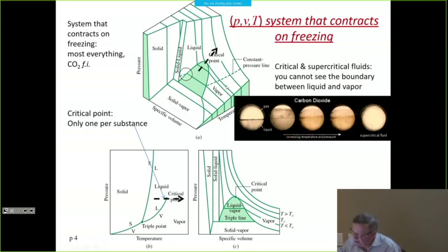Another strange property of most of these gases, liquids and solids is that there is this critical point. And there is a region above the critical point where you're above the vapor dome. In this region, the fluid has supercritical behavior, which is a little bit strange. I illustrate that here in the case of carbon dioxide. If we're here, we have a liquid and a gas that we see quite clearly. As we approach the critical point, this separation line between liquid and gas, which is very clear here, becomes more blurred, more blurred, and in the supercritical fluid, it's completely gone.